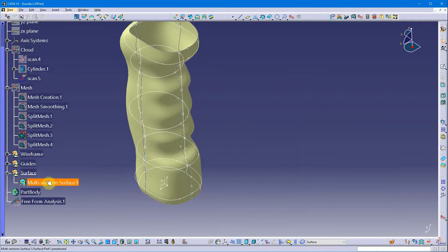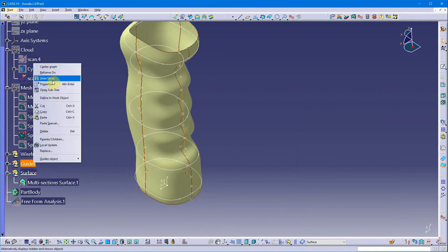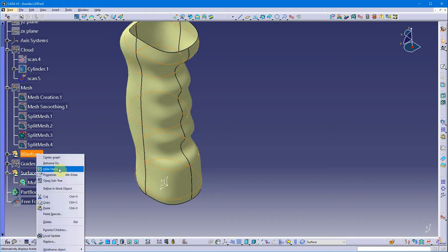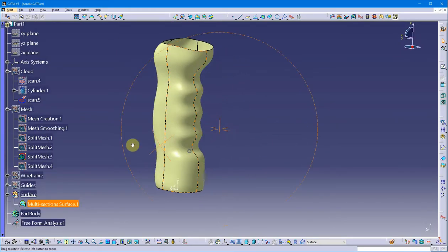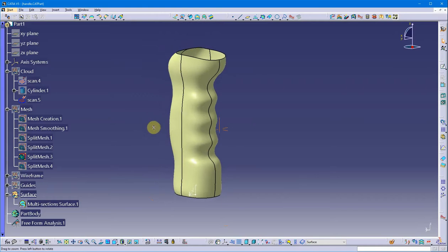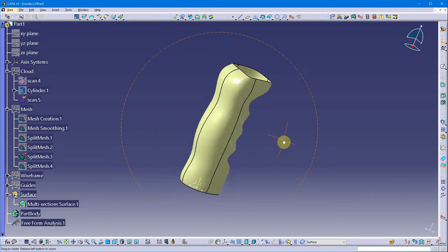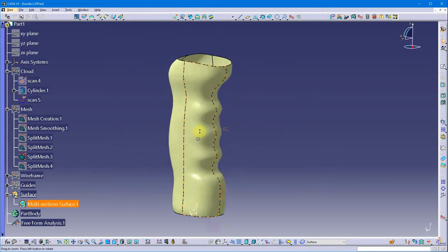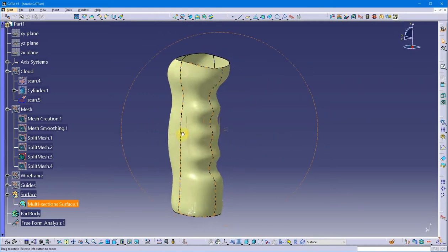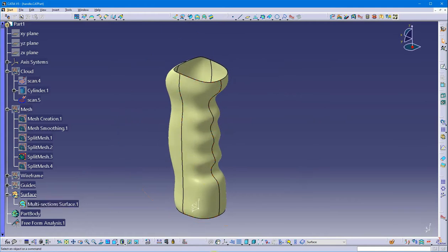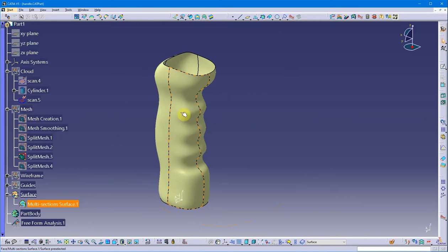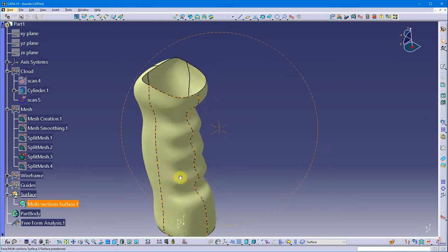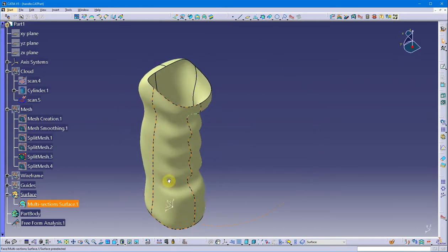Nice, that's a good enough surface. I would spend a lot more time getting it where it needs to be, but it's not a bad surface considering that it started as a clay model. And now I've got at least the sides of a surface model, something to begin with. So that is, again, like I said, clay model, point cloud, mesh, wireframe geometry, and then finally a surface model, a good surface model that's tied to that clay model.